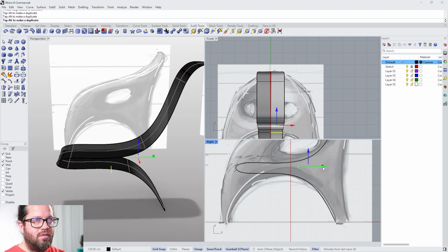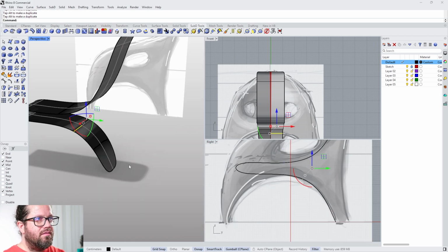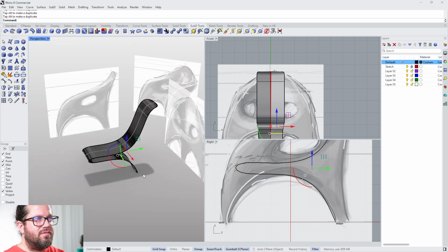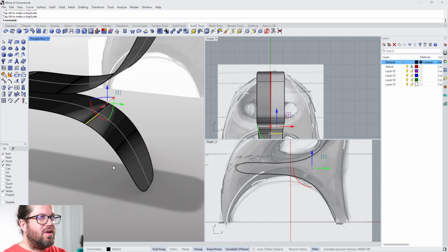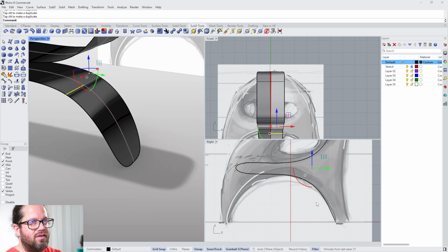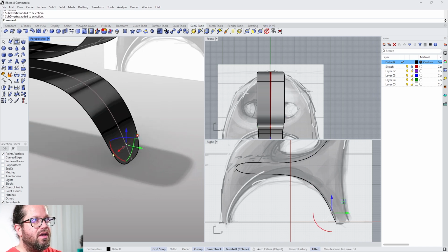And we push this up and probably back. So we can again, well, now I want to explain something very important. We can create creases. Now you can see it's all rounded here as filleted edges basically. I can turn this off locally. I can actually select points and make them creases. I can do that by clicking here on the right, add a hard crease to SubD or mesh.